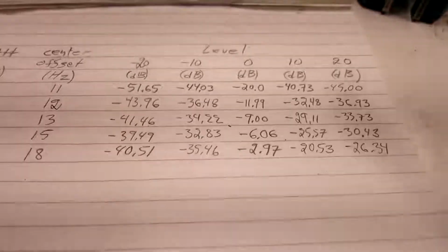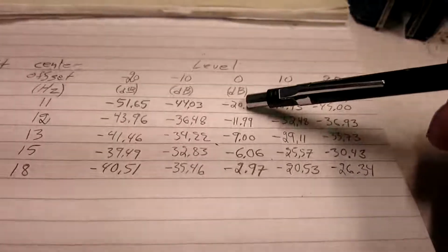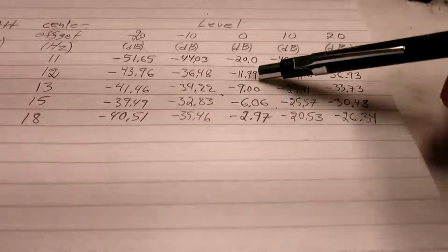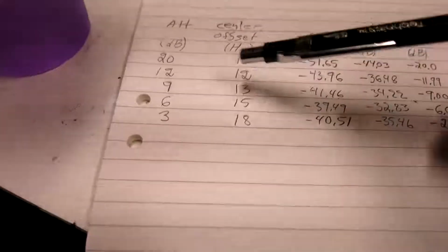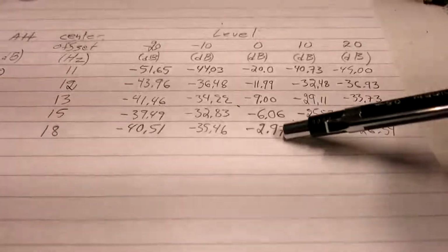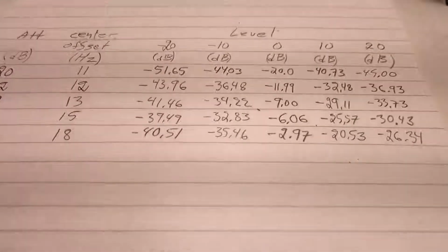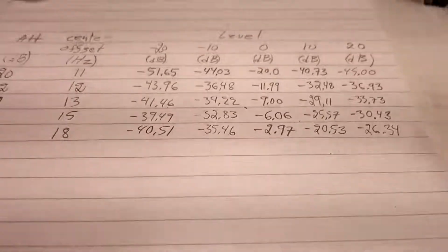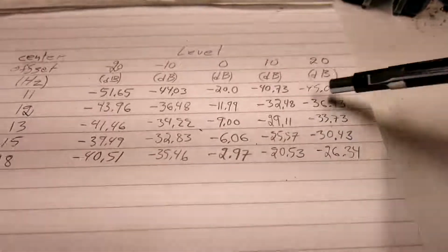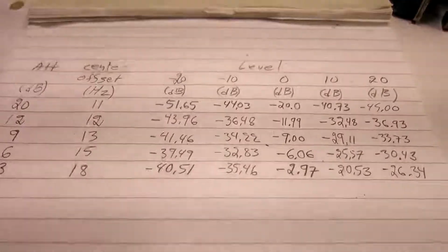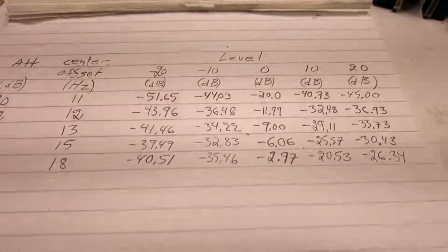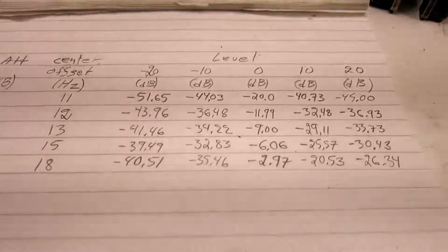The level of the main signal, here no offset, it's close to the nominal attenuation. That's within better than 0.1 dB. So I will just correct the values I have seen here on the sides with the attenuator setting to get the frequency response curves.